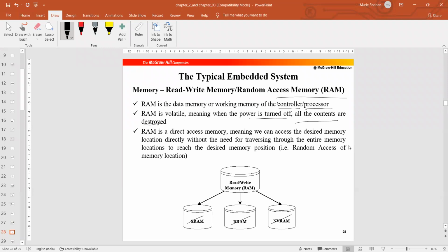Static RAM is designed using transistors. This memory is made only of transistors, FET devices, field effect transistors. So in SRAM, only transistors are used. In DRAM, along with the transistor, there is one capacitor. In electronics, dynamic always means a capacitor, not only in memory but in any context. If you see dynamic in electronic terminology, there is definitely a capacitor inside the device.